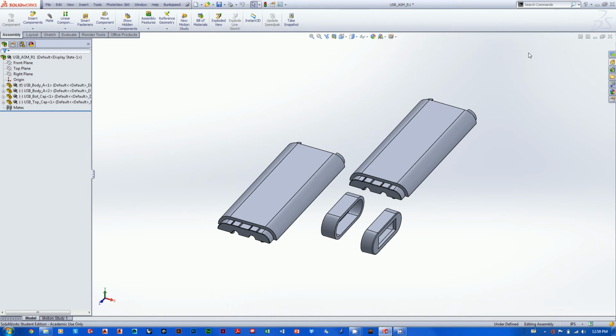Okay, so I'm trying to instill a concept in you guys, which is that when you are creating assemblies, it is very important to keep yourself very organized. Think about what parts you are creating externally, where those parts are saved on your computer, and try to understand that your assembly will be drawing from those files all the time. If you change the location of where those part files are kept, you're going to have to suppress them when you open your assembly, and you don't want that. So you're going to have to go through this little process that I just explained. Okay, so try to keep yourself organized when you're doing part files.